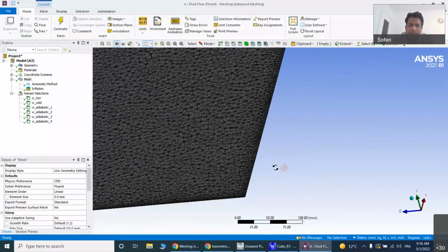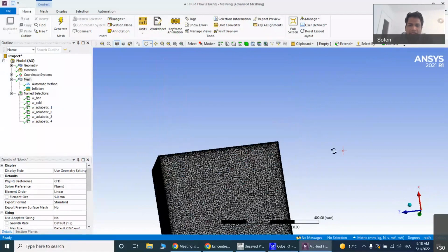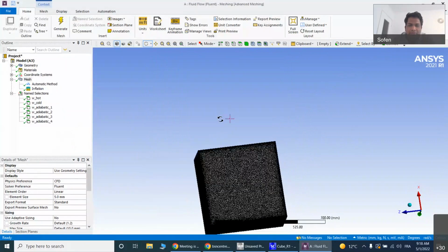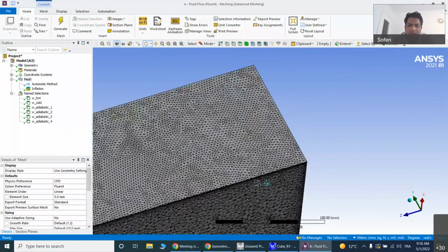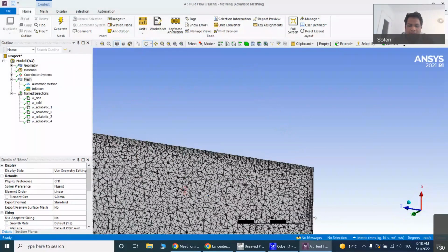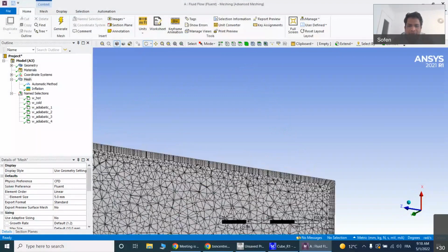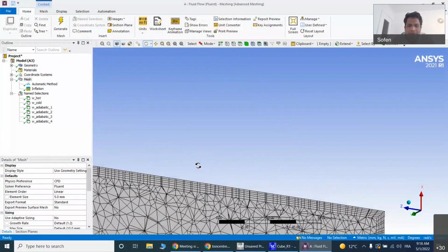Yesterday someone was asking: here it's possible to have some zones with tetrahedral mesh and some with hexahedral mesh based upon the settings. You can generate different kinds of mesh in different zones, some sweep mesh and so on. Again the mesh count will be high. For natural convection we can make some polyhedral mesh, which makes the computation faster.